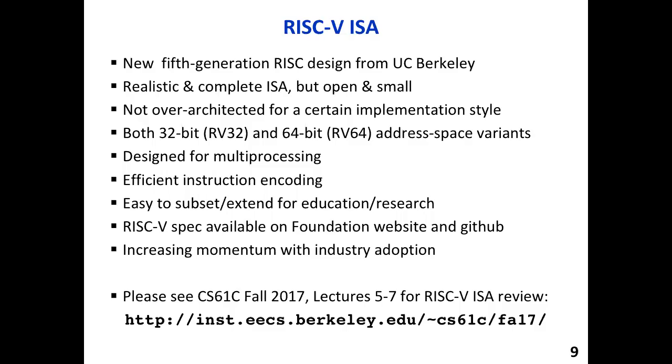And if the RISC-V specification is implemented in something like VHDL, well, hey, I can just take that VHDL and drop it into my DE2 card with my Altera Quartus program, compile it, and now I've got an FPGA that thinks it's a RISC-V processor.